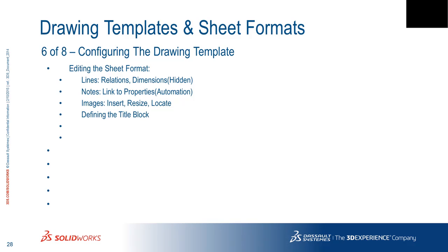You might want to consider taking a look at the task scheduler that comes with SOLIDWORKS. You'll find it under Start, Programs, SOLIDWORKS, probably under SOLIDWORKS Tools, I think. Task scheduler has a way to do exports for you on a scheduled basis. Might want to experiment with that and see if you can set it up to do it in a more automated fashion, but with the multi-sheets, if I was a betting man, I would say I don't think it's going to work real well. You're going to have to try it and see what happens.